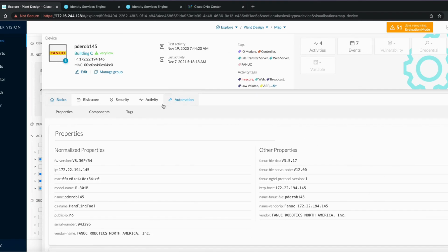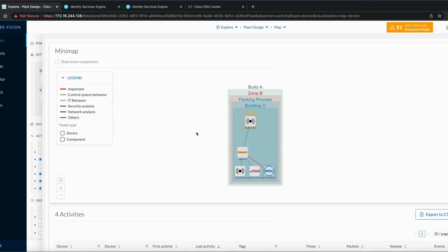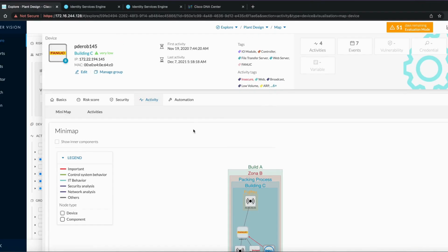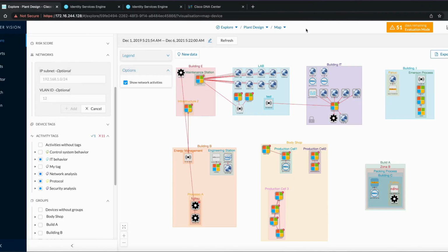You can quickly have a view with Cybervision to see what device is actually reaching the robot and start to create zones easily. So you see I have a building scene, a specific sub-level, but I can see that all the devices that this FANUC robot needs to talk to are in this zone. And I can create this zone, allowing me to make sure I've created the correct zone for my devices. And it's very interactive when you work on these different zones. So you see I can have multiple sub-levels. So this will allow you to really have a clear organization of your devices.